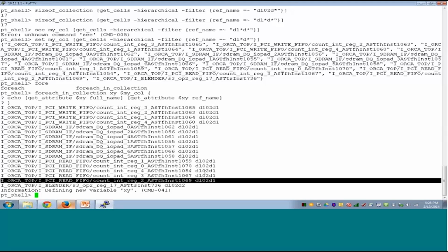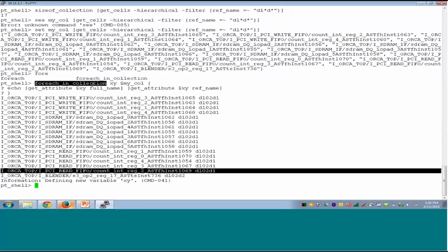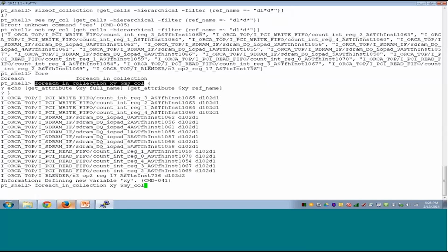Now let's say somebody asks me, what is the area impact of adding all these delay cells? Okay, yes, boss, we have added so many delay cells to solve timing violations. But what is the area increase? So you can do something like this. Again, we will run through each of these collections, and I will calculate the area by using get_attribute of area. What I'll do first, I'll do nothing. I'll set, let's say, DL_area to be 0.